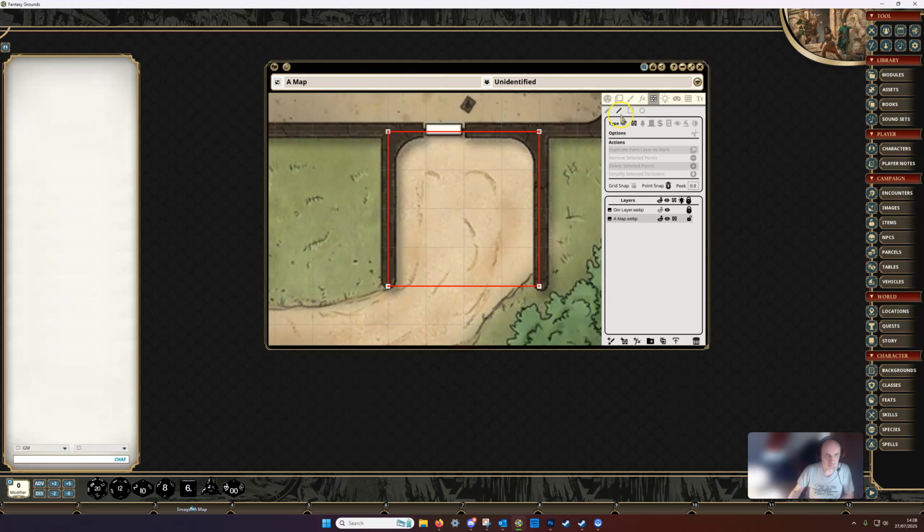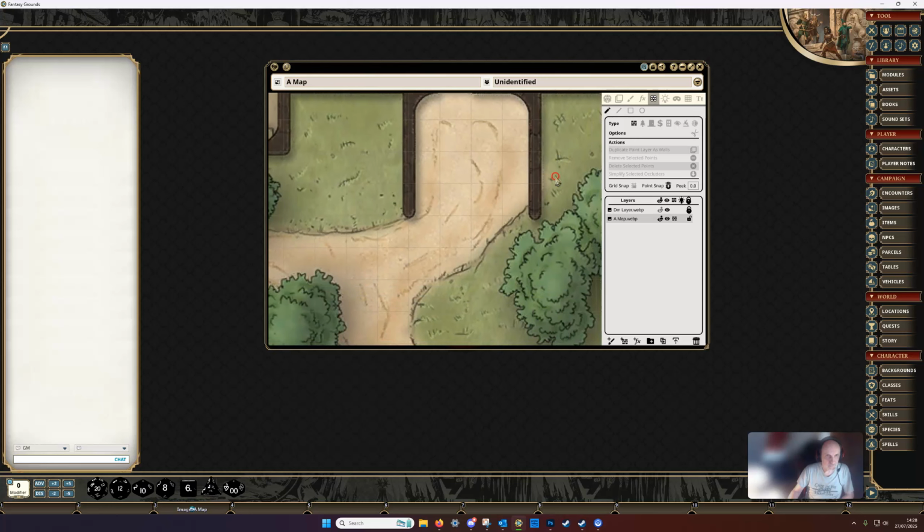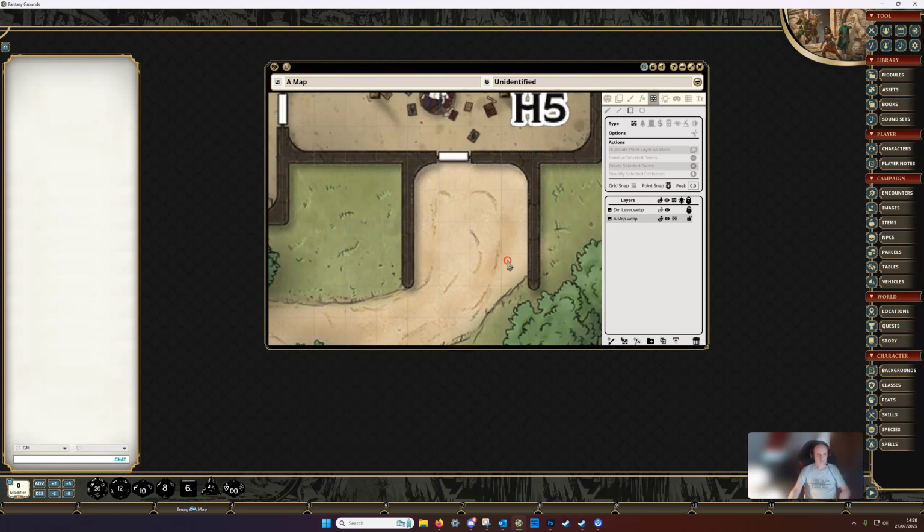Okay, so let's select all of these points. We just select them all and we'll delete them. We'll have a quick look at the rectangle tool. Now, as its name suggests, it will simply draw a rectangle, so we just need to start our point where we want it and keep the left mouse button held down and then just drag, and it will draw our rectangle.